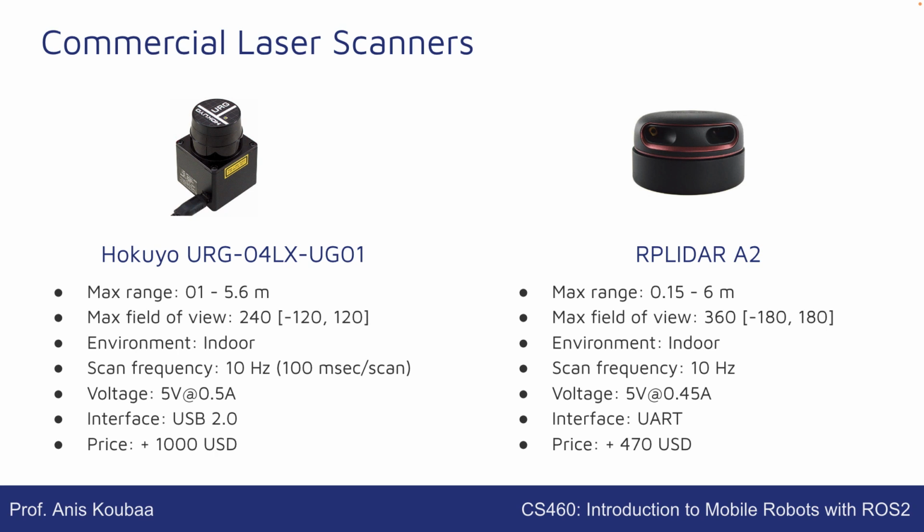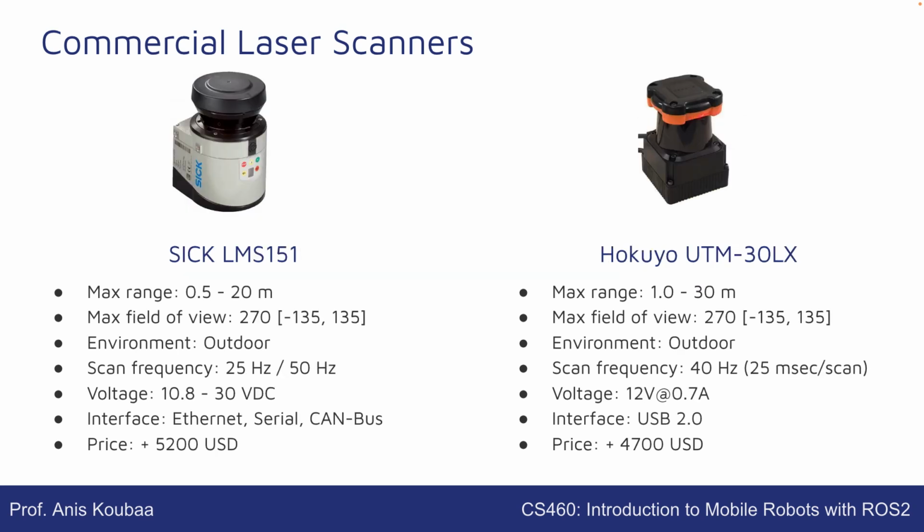It is used for indoor, 10 hertz, 5 volts. So very comparable. This one is used on UART, which is a particular type of serial port, but we can have an adapter to make it work on USB as well. This needs only USB 2.0 because it's only at 10 hertz. If you have a very high frequency, in some cases we may need a higher USB like USB 3.0 and similar.